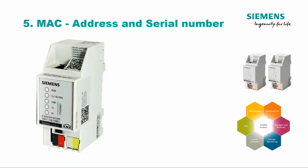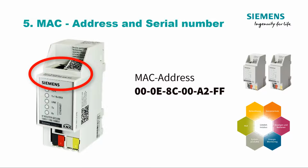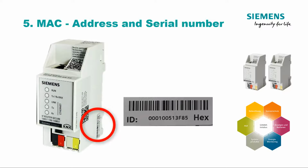MAC address and serial number. The MAC address required for managed DHCP operation and for easier recognition of the product in the ETS communication browser is located as usual on the front shoulder of the housing. The KNX serial number required for assignment of the physical address is located on the right-hand side on the bottom right.